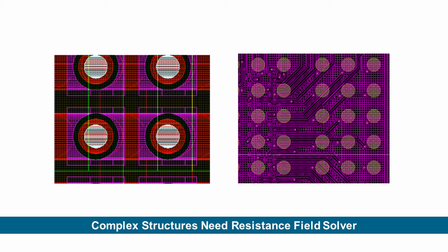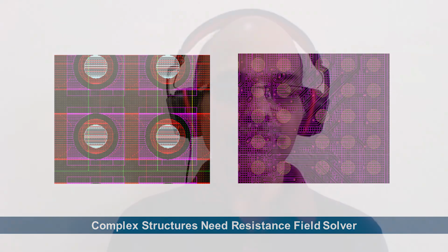Ports provide connections between the RFS and the outside world. There are options that control how to model ports, specify the mesh size, and also to refine the mesh. Various modes of operation are supported as well. Process models including edge and thickness variations, as well as various resistivity models, are accounted for in RFS.